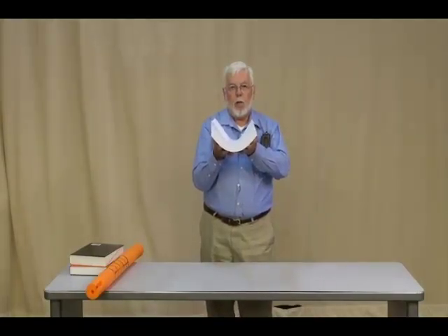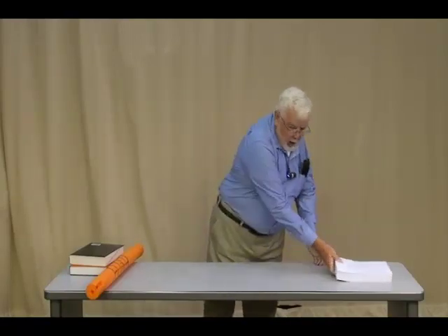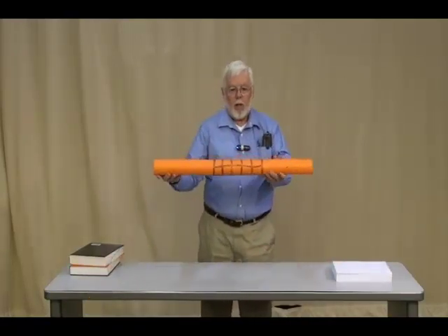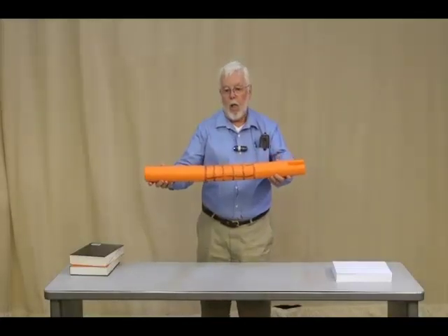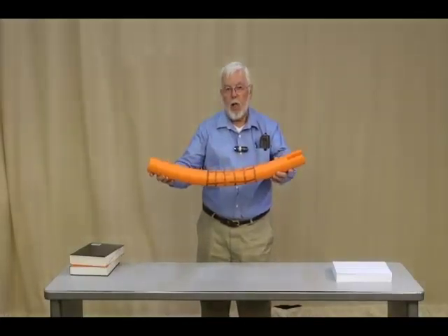Notice that they are still essentially parallel to one another, because in this case I don't have a solid piece of material, but I have a stack of sheets, each of which is free to slip on its neighbor. And what's happening in that slippage is shear. So the sheets are shearing one against the other. And since they are free to move, I don't shorten the top one and lengthen the bottom one. They stay the same length, and they compensate by slipping on one another. Now that slipping motion is short-circuited in this case because we have a solid material. And it can't physically slip, but it's trying to.